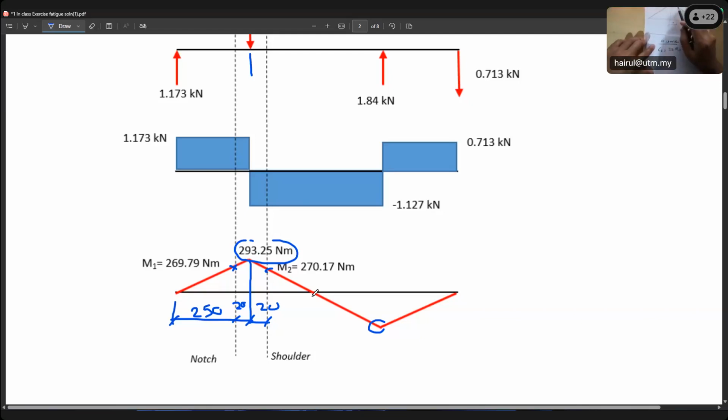Remember this one: at the shoulder, not at the pulley, the shoulder. You can get it from the theorem better. At the shoulder, because it is a shaft, pi d cubed. Which diameter, sir? Take the diameter of the smallest one. We don't take the maximum one, because the maximum is not critical. The critical one is the minimum diameter.